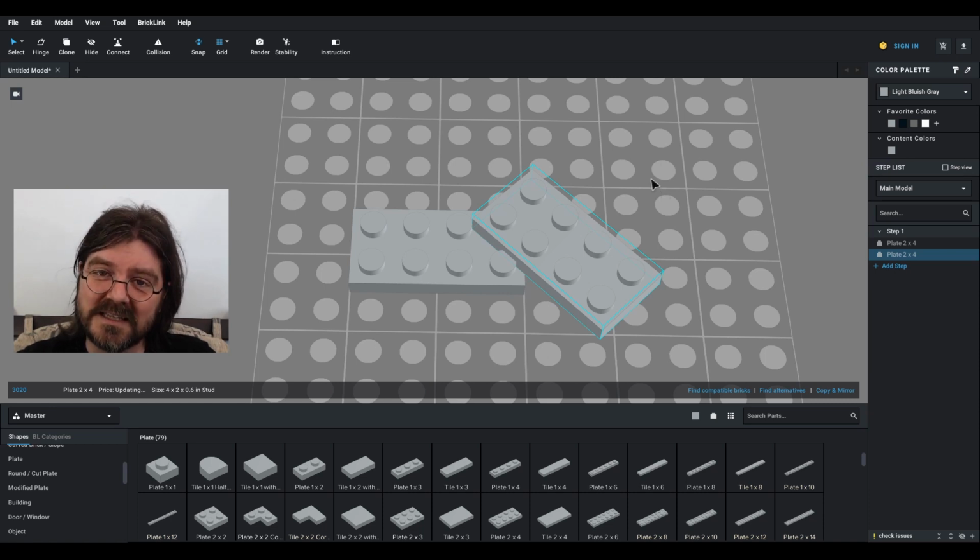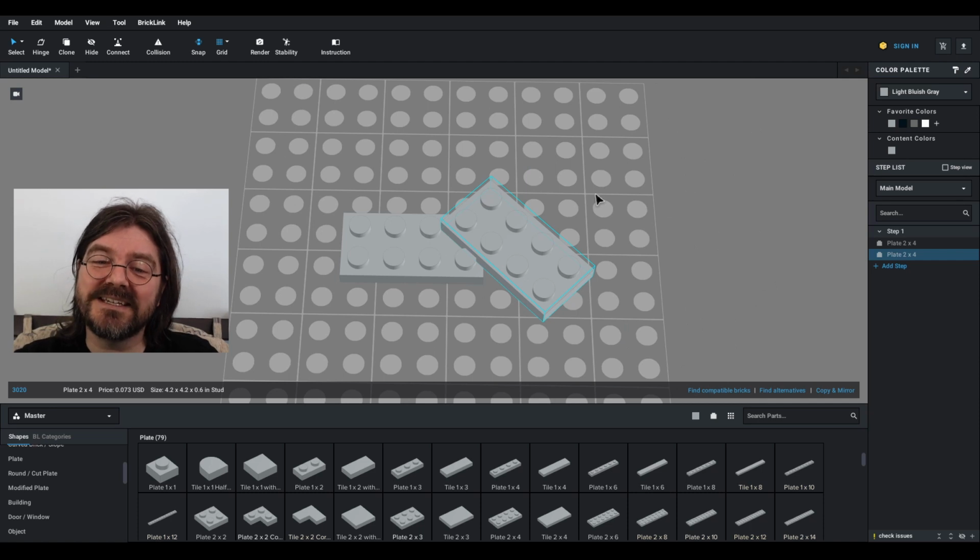If you do want to line them up though, you will have to rotate your object so that it's in the same orientation as the receiver before you use the Connect tool and move it. There has been a suggestion on the Studio forums for 2-point connections where you would first make your connection as normal, but then you could assign a second connection to allow you to line up the pieces.